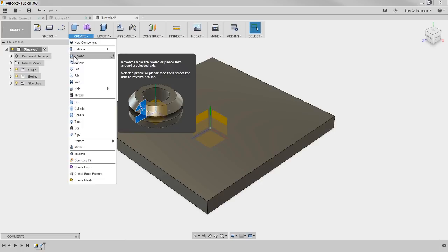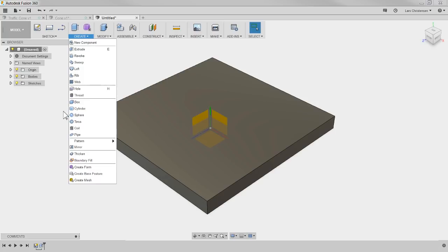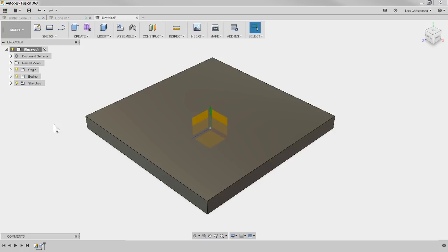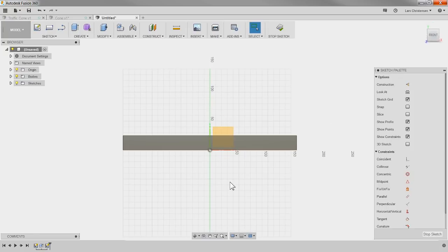And what I'm going to do is I'm going to create a line that I'm going to revolve around. Okay? And revolve is normally side view. So look at your part from a side view perspective. So I'm actually not going to sketch on a face. I'm going to go back again and sketch on this plane over here. So I'm going to open up a new sketch, 2D sketch. I'm going to select on this plane over here. You'll see how it's rotating to the side view. And I'm going to draw a line to rotate around.